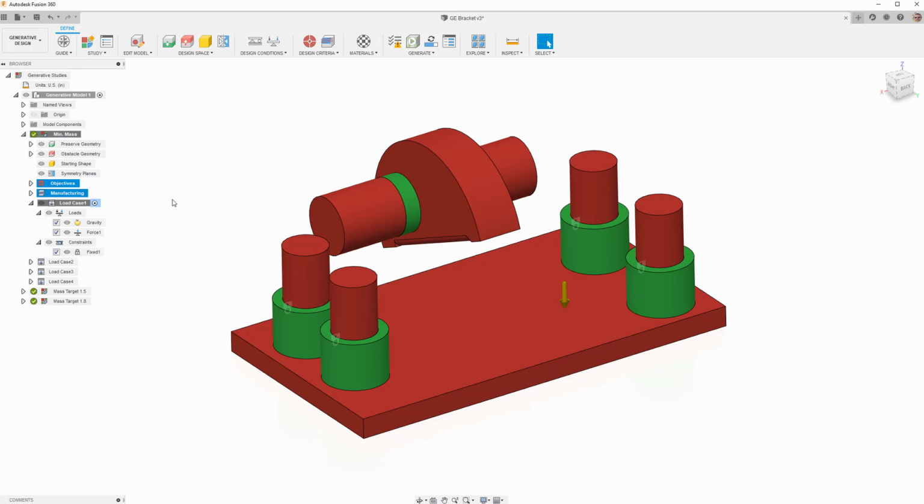One more note on loads. I found this out with some of my generative additive 3D printed parts that I've made. I have often missed a few loads. I've built a bracket where it has to support a certain amount of load in a direction, and maybe there's some side forces sometimes, and I'm assuming that these pins are fixed in place. But during installation, I've found that these pieces aren't fixed yet. So I'll start fastening one, and then I'll start fastening the other, and I'm realizing that I'm flexing this plastic part incredibly.